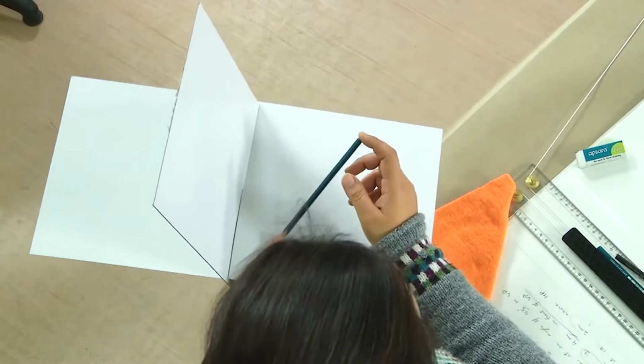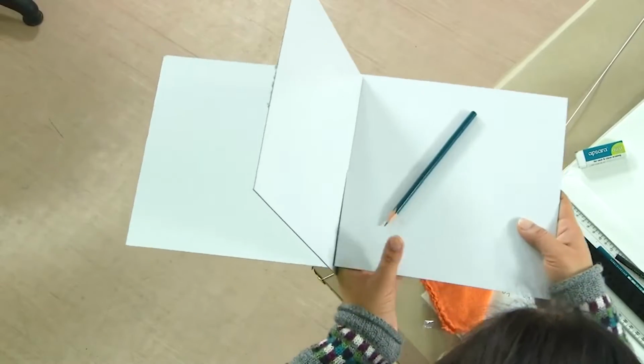So, if you essentially see, if it is inclined to one plane and we want to incline it to the other plane, we are moving it in a cone-like manner. So, let us understand this with the help of a cone. The movement is like that of a cone. Suppose there was a line which was making an angle of say 45 degrees and now it has to make an angle of 45 degrees with VP as well. We will raise it in such a manner that it moves like a cone.